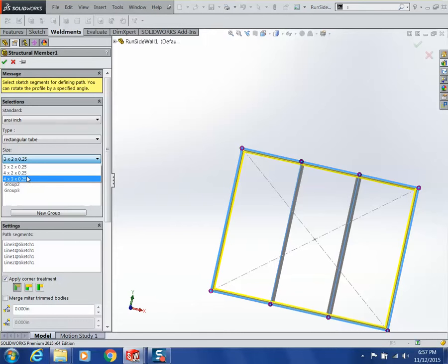So any sketch that you have in SolidWorks, you can turn into a weldment profile. Be it a 2x4 or be it 80-20, it doesn't matter. Define the sketch. Once you have just the sketch, you'll make a SolidWorks part, make the sketch, do a file save as.